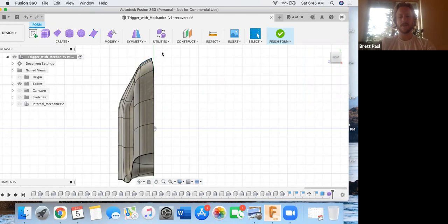Okay, so in this case, these panels and these segments and points were the only things inside that box. I'm going to click escape and do this again. Now, if I click down and to the left and we have the yellow box, it's going to highlight everything that it's touching. It doesn't necessarily have to be fully inside it. Only if it touches or intersects it will it highlight it. So we're going to see that a lot more panels with the same box are going to be highlighted. At the beginning we only had these two, and now we have all of these because they all intersected a point or a region or a portion of that yellow box.